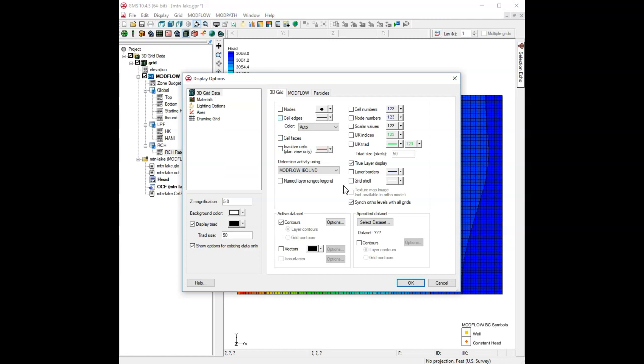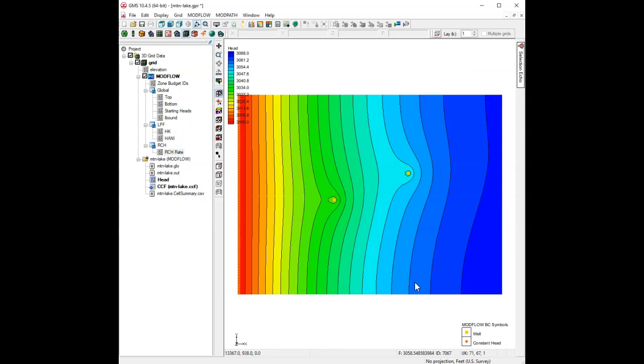So anyway, you could continue to play with some of the different options here. But hey, we were able to create a simple MODFLOW grid, create a simulation, add a well or two, and look at what happens when we change the hydraulic conductivity and recharge. This has been a nice little introduction to MODFLOW. And so we'll stop here and we'll come back later with another set of exercises to keep on improving your skill with and exposure to MODFLOW models.